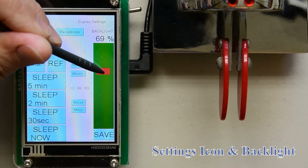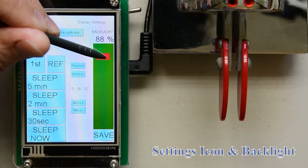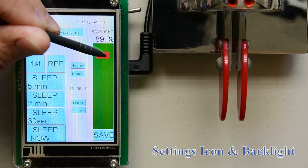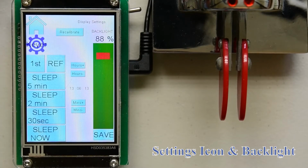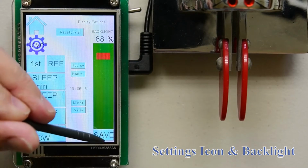If you tap the thumb, you can set the backlight level to whatever you need. Backlight is one of the biggest power hogs on the keyer, so if you are operating on a battery, you might want to set that down. The backlight setting will remain throughout the entire time you have the keyer on, but when you power down the keyer, it will go back to whatever its last setting was. To retain the setting you've just made, tap the Save key.